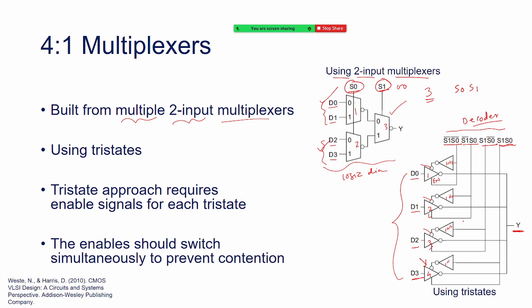But the question again, can we use compound gates to create this 4:1 mux? Yes, but that would be a complex function, so many logic gates, a large number of transistors, an inefficient design. I repeat, inefficient design. And that would be, again, a very important statement, non-restoring logic. It will work, but degraded outputs may appear at the output, or speed will be less, it will not be compact. But this network using tristate, you can create that.